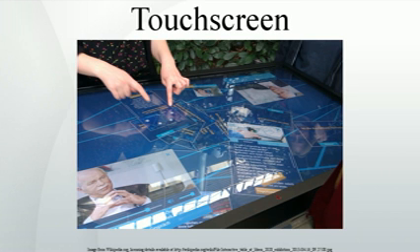Unlike capacitive touch screens, infrared touch screens do not require any patterning on the glass, which increases durability and optical clarity of the overall system. Infrared touch screens are sensitive to dirt and dust that can interfere with the IR beams, and suffer from parallax in curved surfaces and accidental press when the user hovers his/her finger over the screen while searching for the item to be selected.